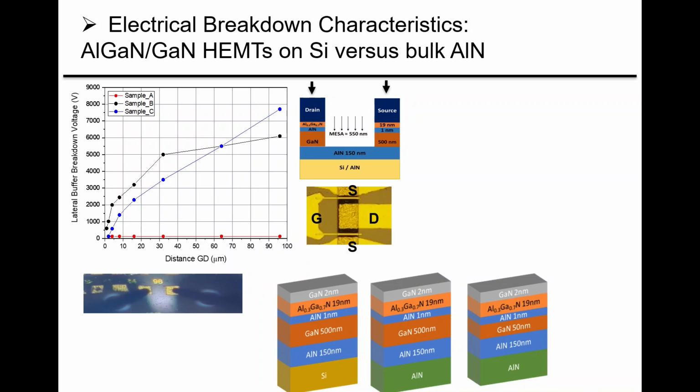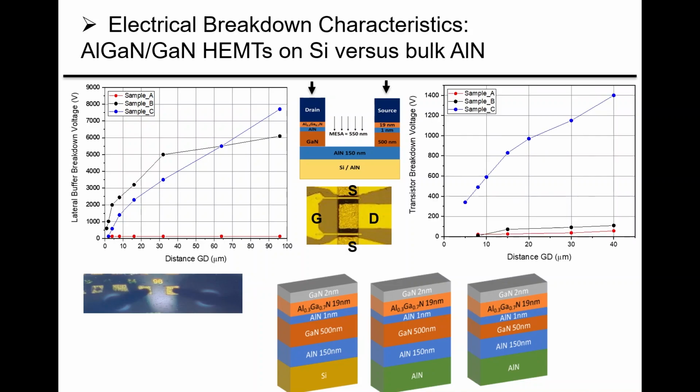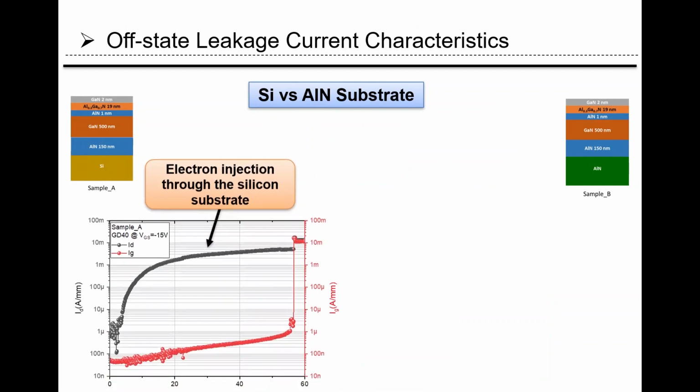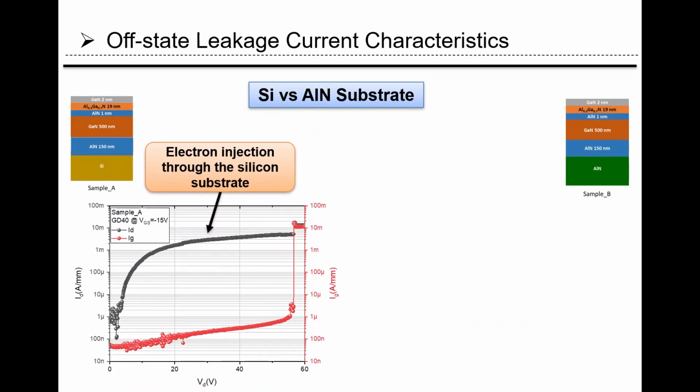Okay. Just quickly here, this is the transistor breakdown. An interesting point is that if you use thick gallium nitride, you suffer from the gallium nitride actually here. I will explain that quickly. And if you make the gallium nitride thinner, you drastically increase the breakdown. This is very easy to understand. That's the silicon transistor, thin GaN on silicon.